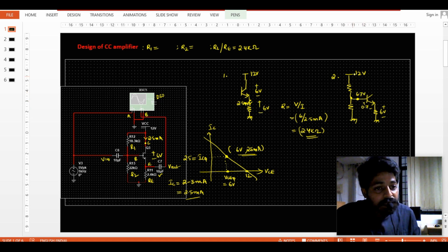So as I can say, this is my biasing circuit. It needs to generate this much voltage. From this, I can say this is just a voltage divider network, where it divides the total voltage by R2 by R1 plus R2 times the total voltage. Around 12 volts is applied, so the total voltage is divided by this fraction, and we expect around 6.7.